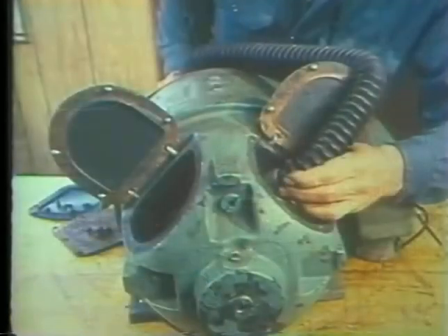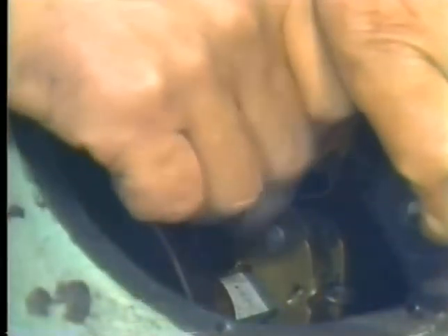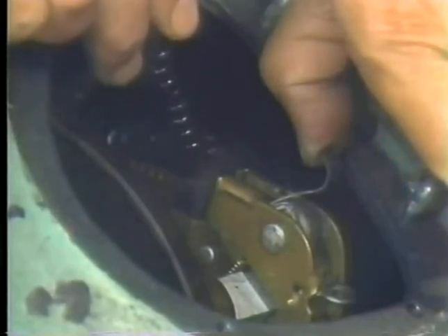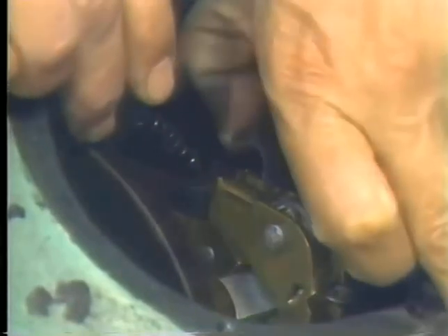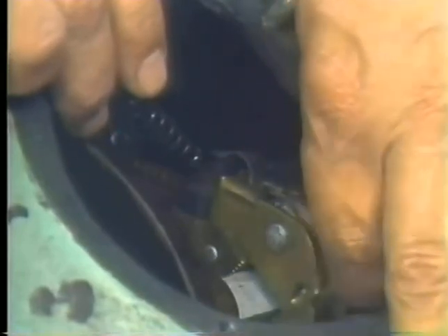Be sure you remove any carbon dust in the motor afterward. All right. At this point, your brushes are ready. Your motor is clean, and you can begin to reinstall the brushes. Start by moving the brushes up and down in the holder to make sure they're not hung up somewhere. Then set the tension devices.